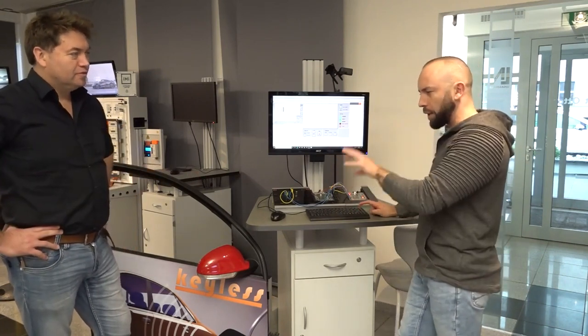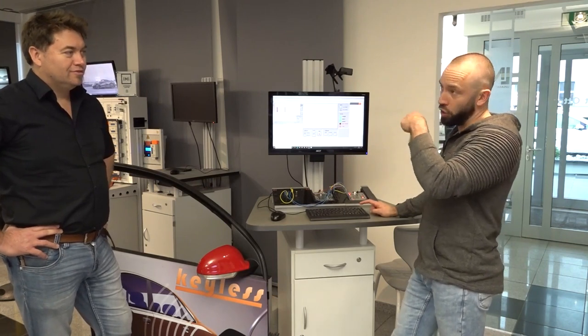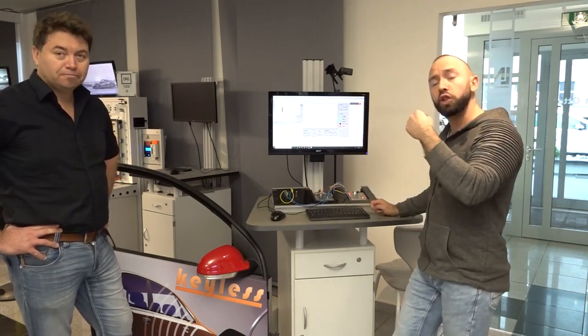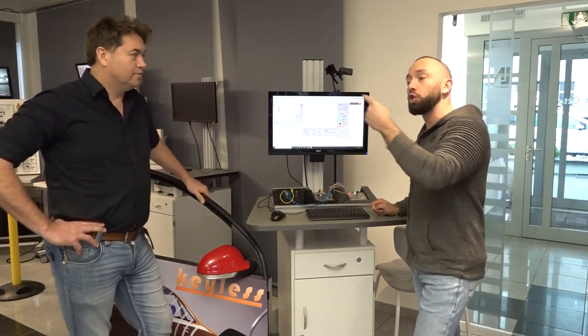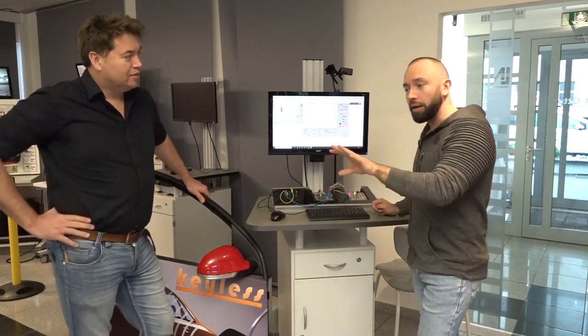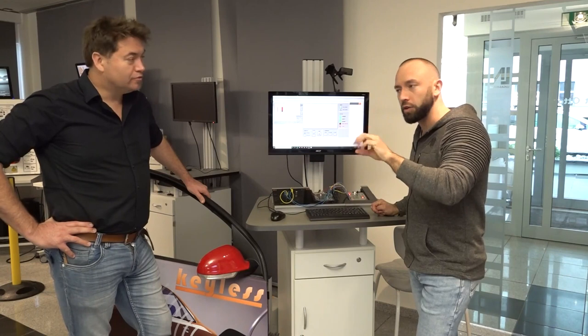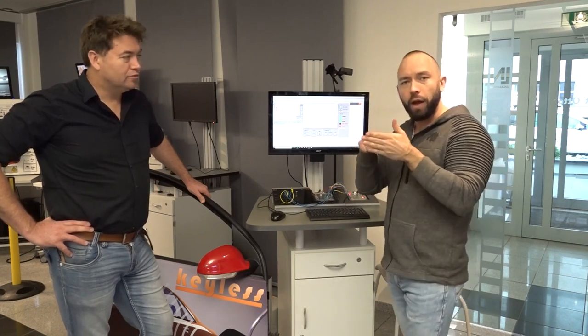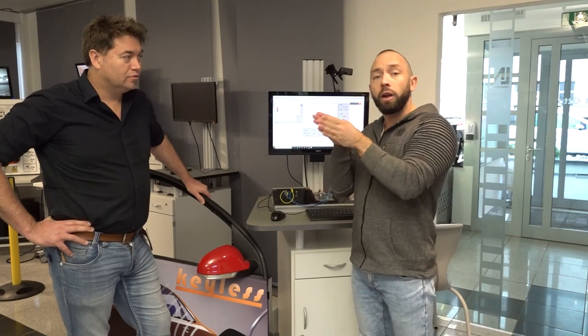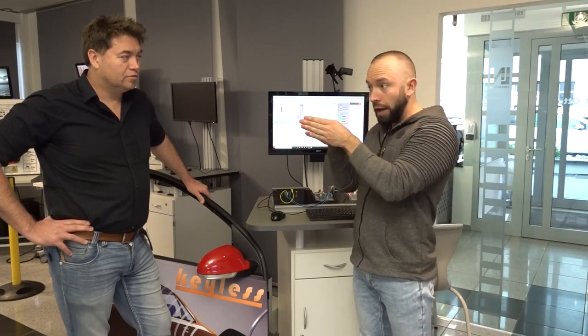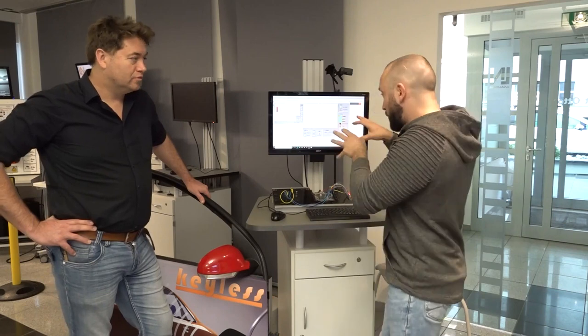The CAN bus is basically a very safe system as long as you are not a CAN node, or as long as you do not connect as a CAN node to the system itself. So that's why sometimes when you have funny pictures on the internet where thieves try to capture a car, they really sometimes try to bore a hole in the door in order to access the CAN node at the door. And when you are able to do that, that you become a CAN node, or that you can access the CAN node, then you can send signals on the CAN bus, and the car will accept them, as you've seen here right now.